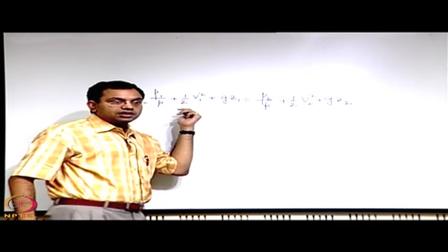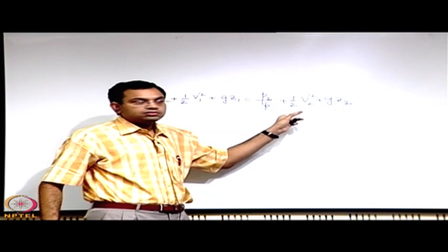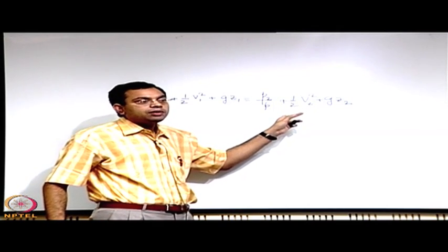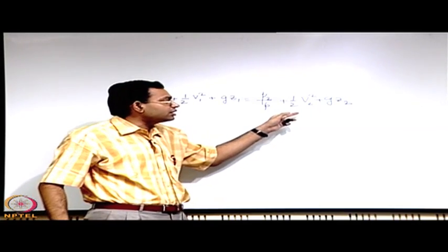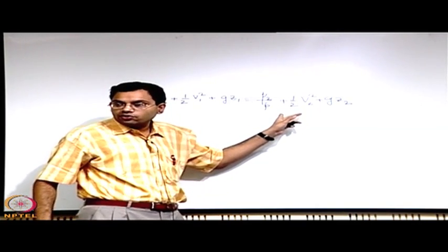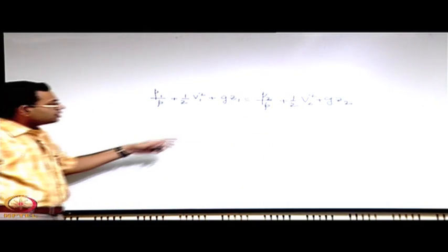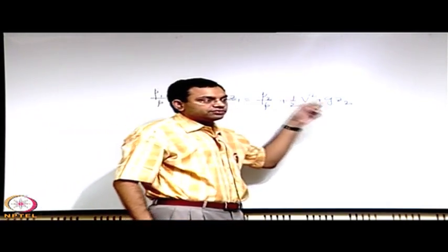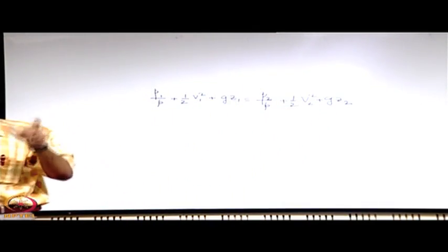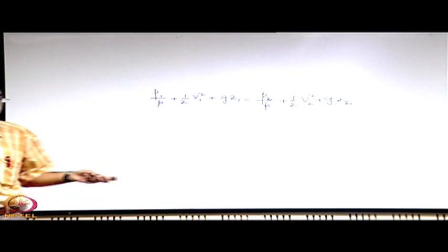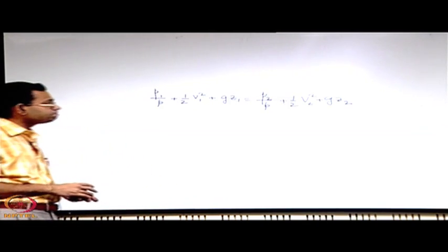Density is constant and we derived it along a streamline where it requires no other restriction, but if you want to apply between any two points which are not necessarily located on the same streamline, then it has to be irrotational flow, or maybe a special case when the cross product of the velocity with the vorticity is perpendicular to the line element that is being chosen. So, these are some of the discussions that we made in the previous lecture.